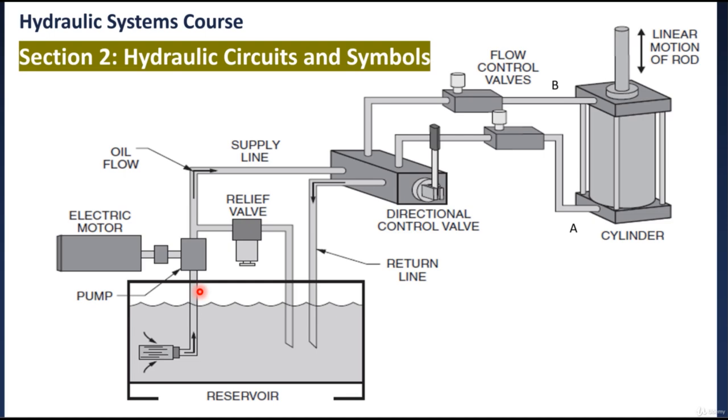And here we need to be careful on this statement, a constant volume. This constant volume will be produced in each revolution of the pump shaft. Therefore, the fluid pressure can increase indefinitely at the dead end of a piston until the system fails. So the pressure regulator here is used to avoid such circumstances, which redirects the excess fluid back to the storage tank.